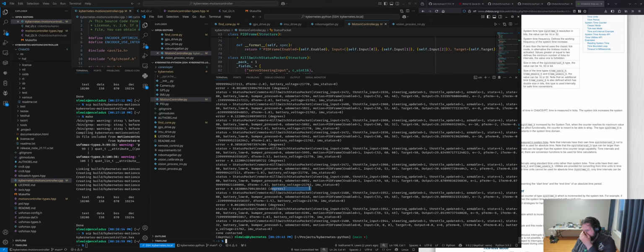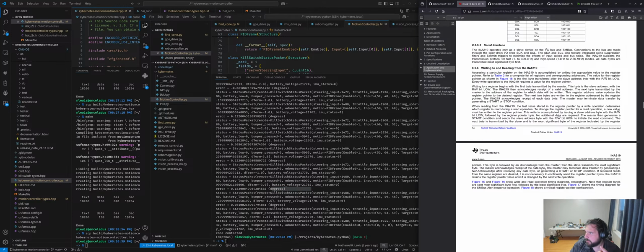Okay, cool. So the problem is that in a lot of data sheets, the I2C addresses are written as 8-bit quantities, even though they technically only have 7 bits. The I2C address is an 8-bit field, but the last bit means read-write.